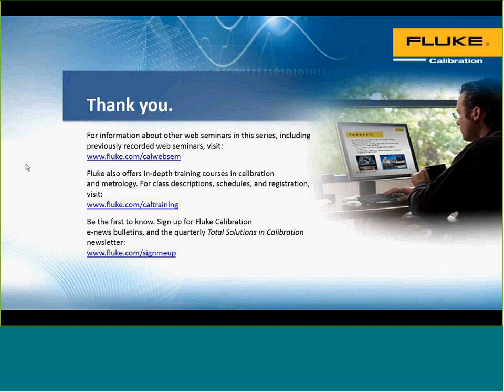If you were to change it out at your site, you would purge out the fluid it was manufactured with, and similar density fluids will work that way. It is very important, if you have to change out fluid due to cleanliness issues, that you purge it properly. But typically the controller is made for a specific fluid.